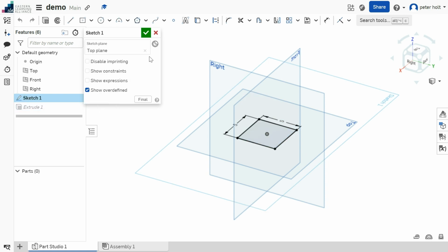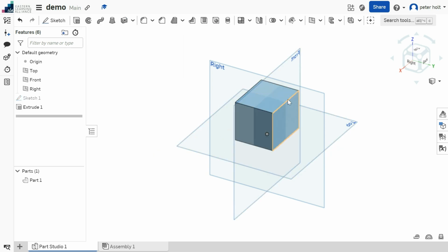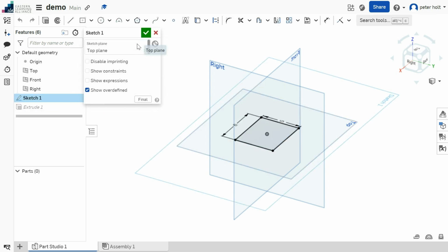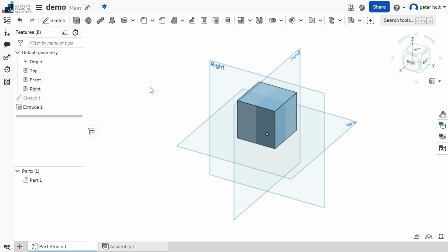And if I go in and edit my sketch, let's say I change this to 6 for a moment. If I go and edit my sketch and say thank you, it will also edit the 3-dimensional shape. I'm going to change that back again by double clicking on there, pressing 5 and pressing enter, so it's changed back again. I click tick to close the sketch.